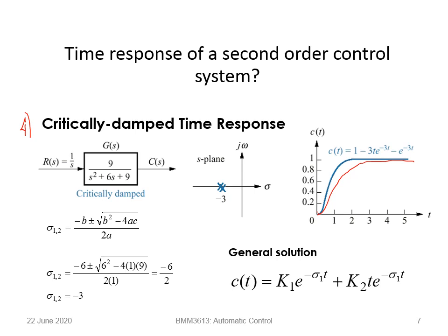So basically this is a critical point, critically damped, where if the position of the poles changes a bit. What does it mean to change? Because now the poles are at the same point, if you have them separated into two different points on the real axis, you will have the overdamped case.